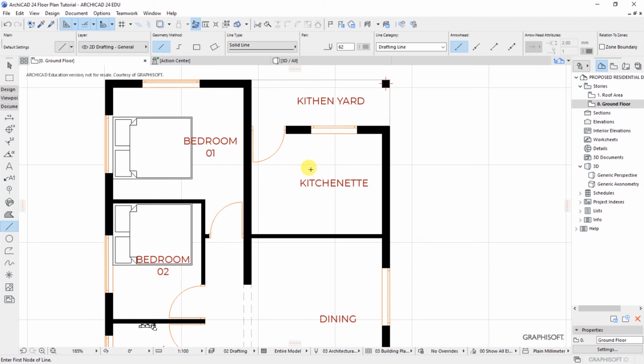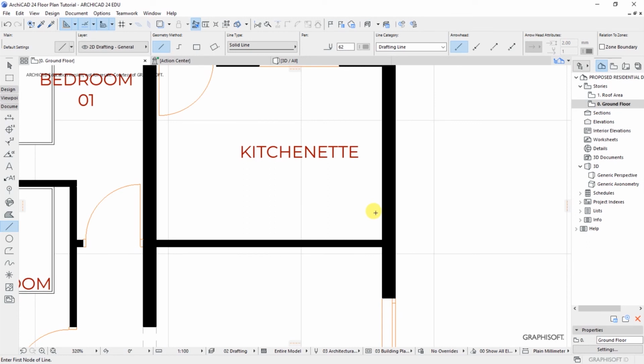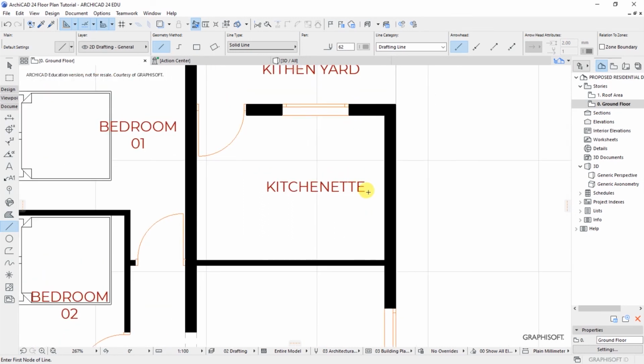So this worktop is going to cover the entire of this area. It's going to be an inverted L shape, and from the wall going to be 600 millimeters from this wall. So we're using a line. I'll be able to now mark where 600 millimeters is.